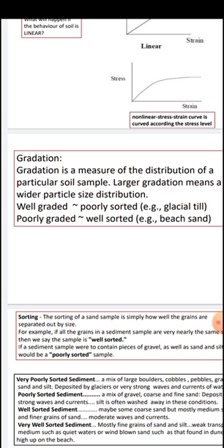In this case, in a more graded structure, the pores between the soil particles are normally filled up with the finer particles. So that means we have a lesser void ratio, and that means the passage for movement of water from top to bottom is not so easily available to facilitate the movement of water through these pores or voids.